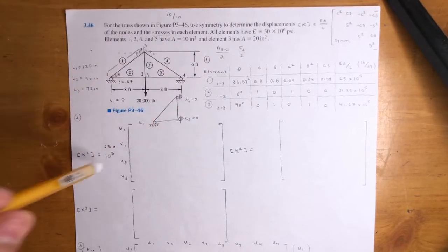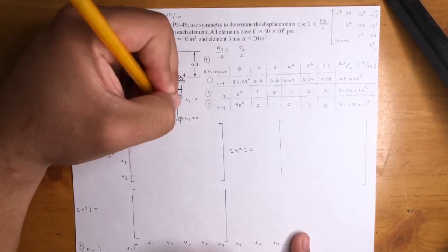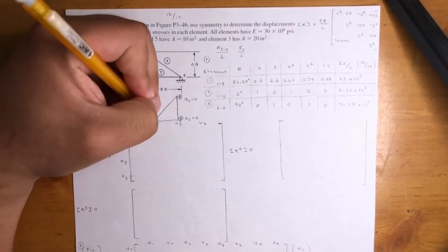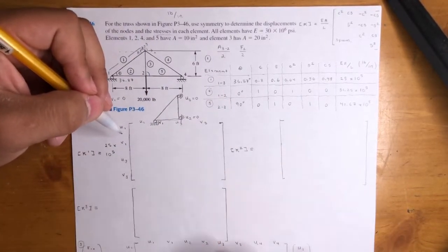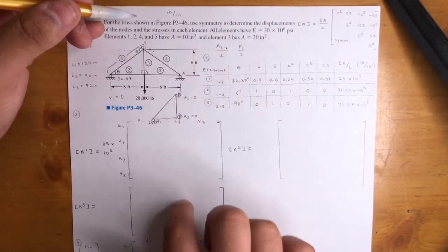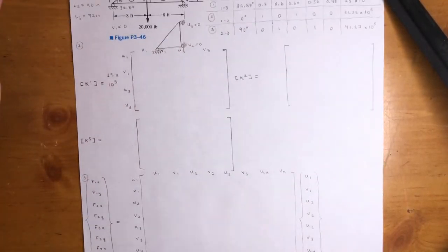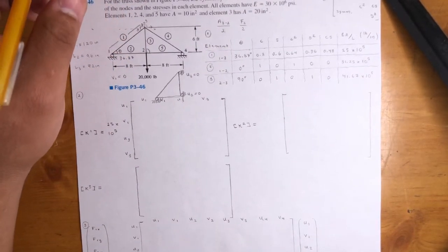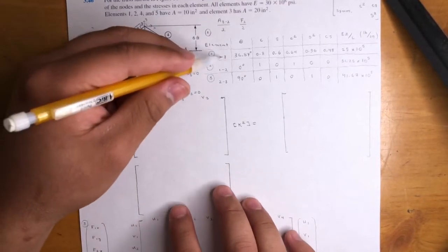I'll just do this, hopefully you can see it. U3, V3, and that's V1 right here. So, what was I saying? Yeah, normally it's not going to change your global stiffness matrix, but when you start looking for stresses, that's when it's going to screw you up. So you'll get this part right, and if you only ask for the global stiffness matrix, I guess you dodged a bullet. But once you start looking for stresses or forces, you're screwed. So just be consistent: U1, V1, U3, V3, because we chose that order.